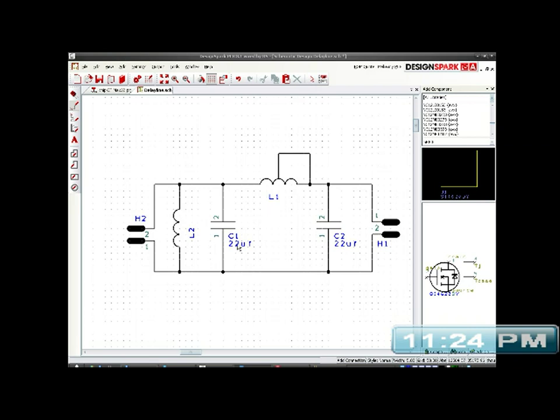I got such a big difference by changing between 22 microfarads at this point here and 47. Putting 100 microfarads on here made everything slow down a lot. It just really lagged because the pulse was just non-existent really, and there was loads of drag. But I got good results between about 10 microfarads and 22 microfarads.